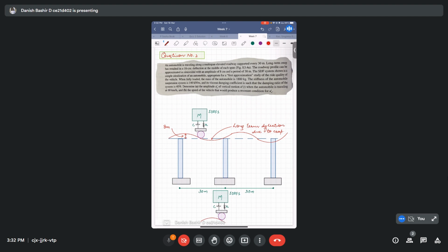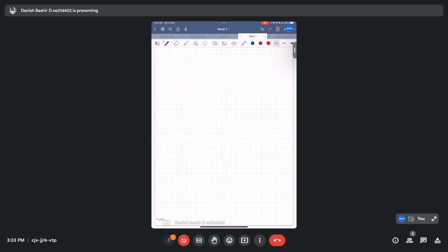Okay, so there will be vertical motion or vertical displacement ug. And what will be transmitted in this single degree of freedom system of a vehicle? Okay, basic things. We can do it like this. We will assume the tires are infinitely stiff and they remain in contact with the road all the time while the vehicle passes through this roadway.